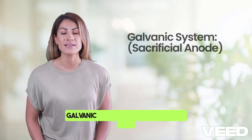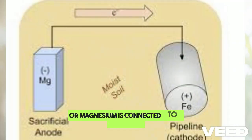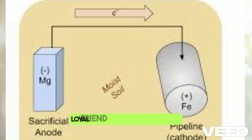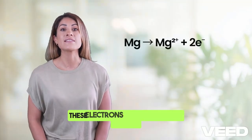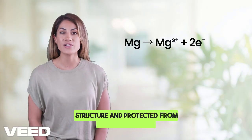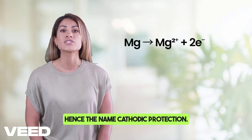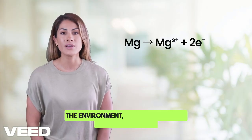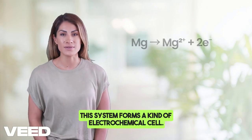One, galvanic sacrificial anode. A more reactive metal, like zinc or magnesium, is connected to the structure. It corrodes instead, sacrificing itself, like a loyal friend taking a hit for you. Instead of ferrous oxidizing, we force another metal to oxidize, like zinc, magnesium, or aluminum. See this equation. These electrons are gained by the ferrous structure and protected from oxidation, so the protected structure becomes the cathode, hence the name cathodic protection. The environment, soil or water, acts like an electrolyte. This system forms a kind of electrochemical cell.